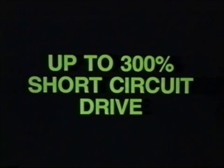Another advantage of an excitation support system is that it can supply to the automatic voltage regulator sufficient power to drive the exciter to its ceiling and enable the alternator to sustain up to 300% short circuit current flow.